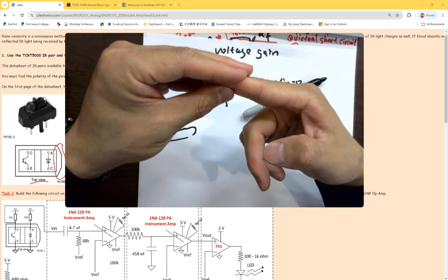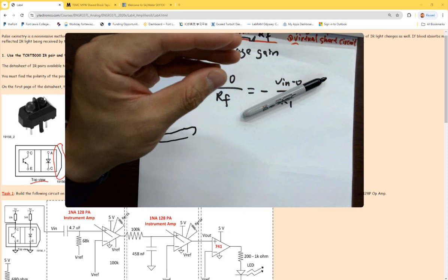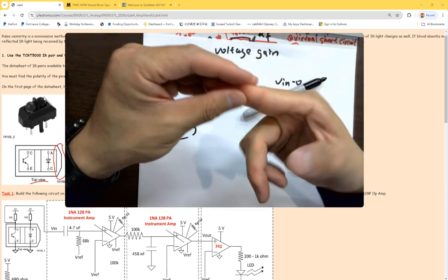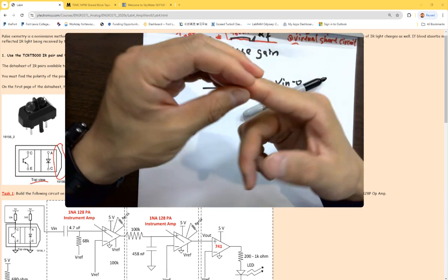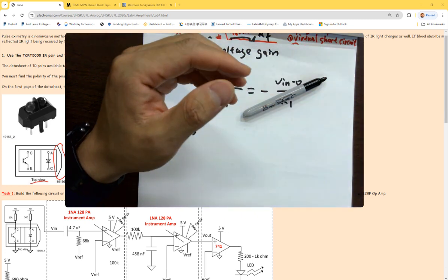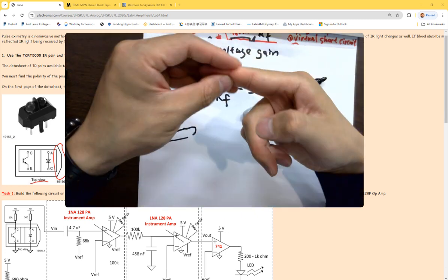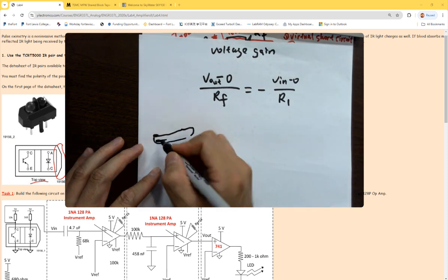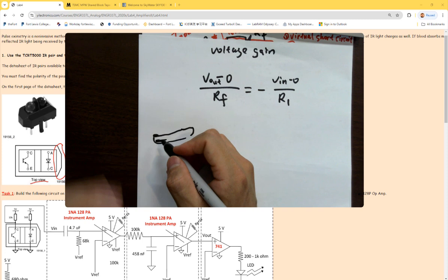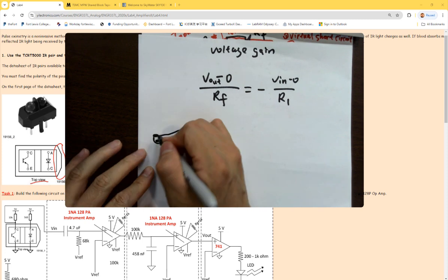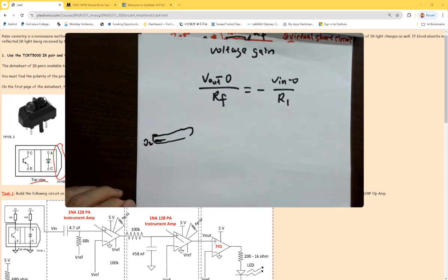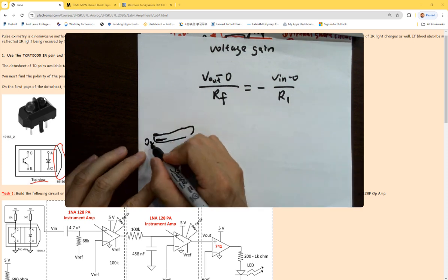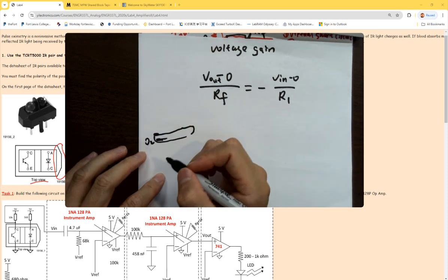Put the finger in and you can see a pulse as well. So it's not collecting voltage, you have to know that. It's not collecting voltage like the ECG signal, which collects the voltage and amplifies it. What this one does is, your fingertip has blood vessels, right? So the blood is going to absorb oxygen. So it has oxygen inside your blood. And oxygen absorbs IR light.